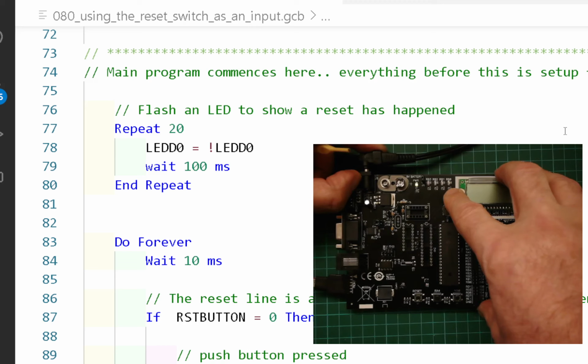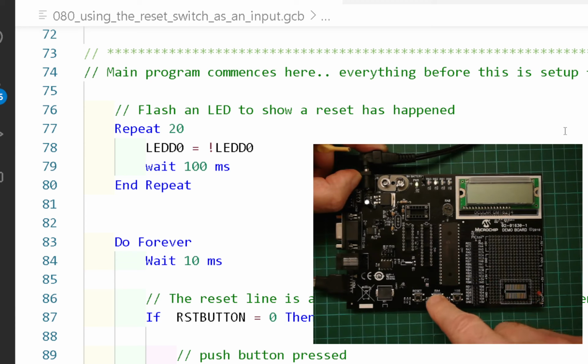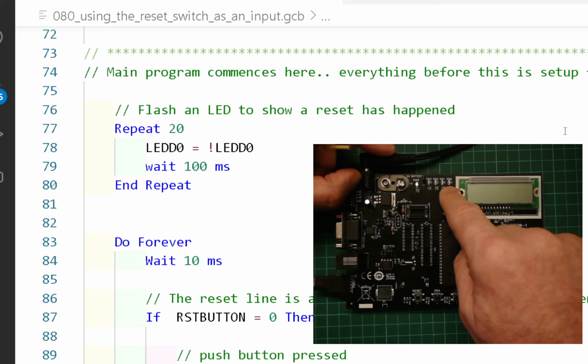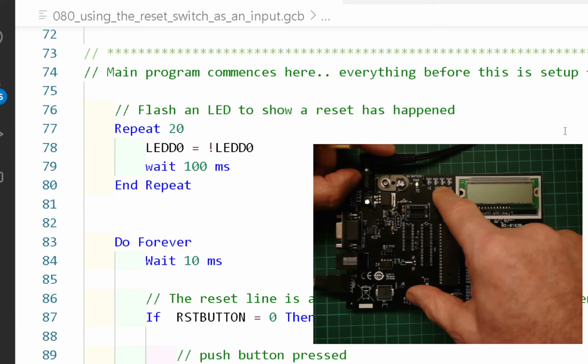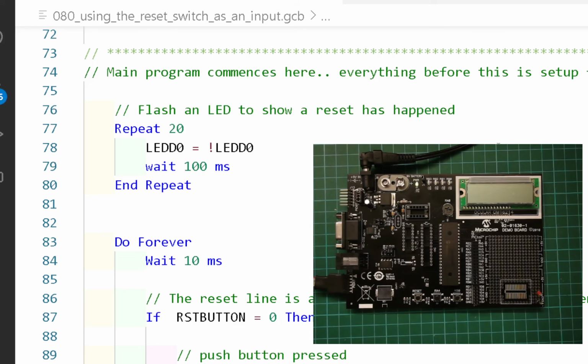So we now know that when this chip boots, it flashes 10 times. If I press RA4, the button comes on, the LED comes on. If I press the reset, which is the left one, I get RB1 come on, which is this other LED. So we've got 3 LEDs here. This one on the right will flash when we reset the chip. This will flash when I push the reset button, and that's clearly changing it. It's not crashing because it's not rebooting, because the first LED is not being lit. Finally, RB2. Let's change our program.